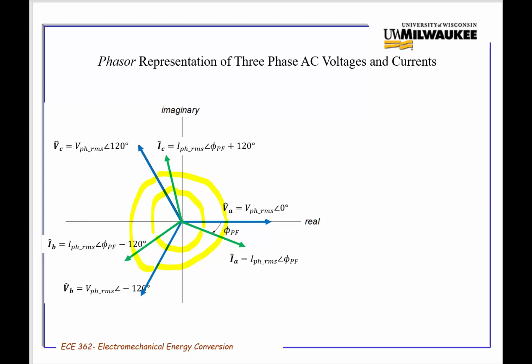We're going to use it to figure something out mathematically about this balanced load that we are putting onto our 3-phase source. So I'm going to attempt to grab this vector. I've got my IC vector, IB vector, and I'm going to add them together by connecting, well, let's go in ABC direct.